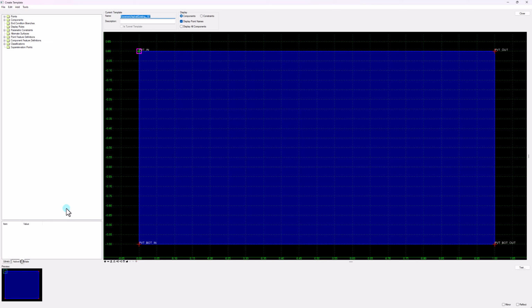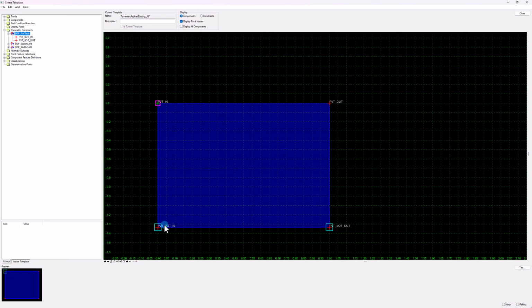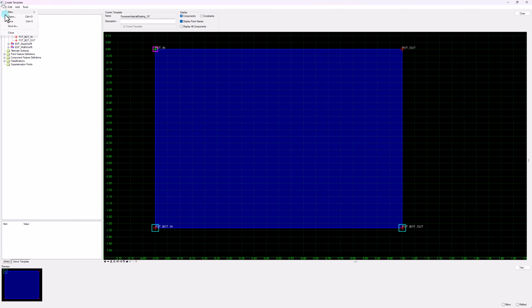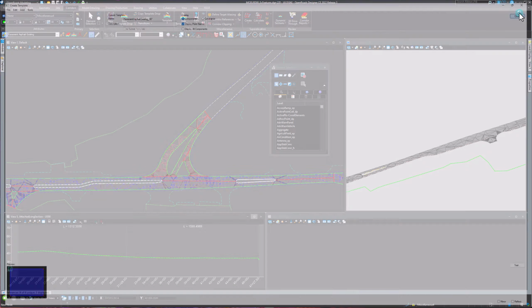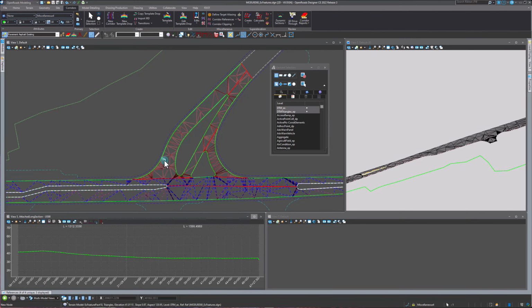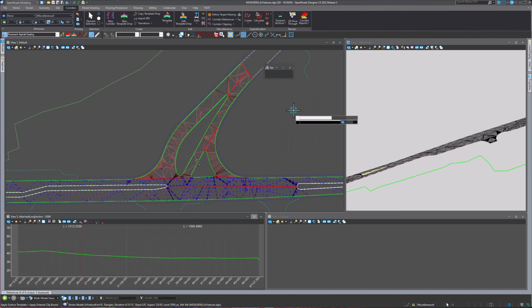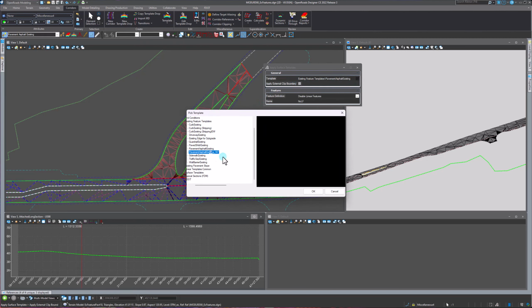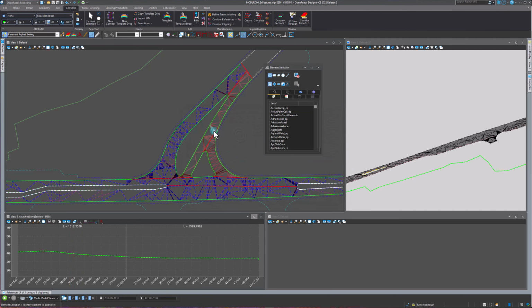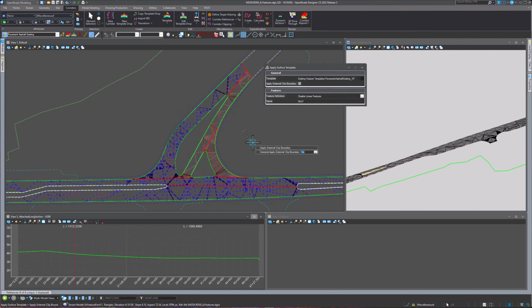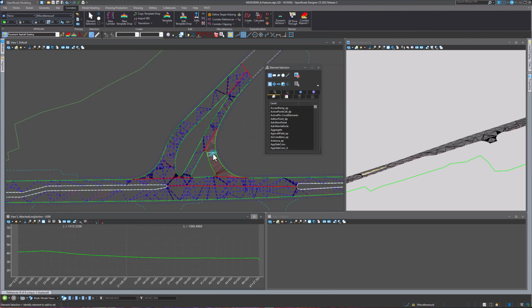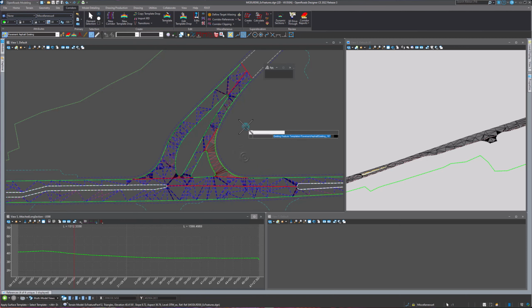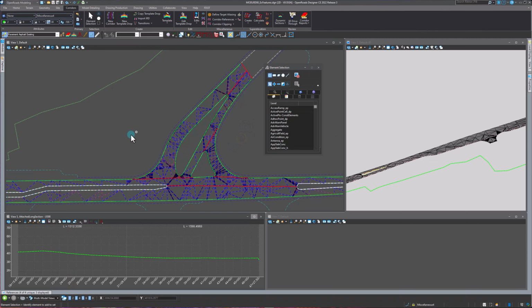And like I said before, you could go into this active template, go to those parametric constraints, and this still works within the template. So if I click on that and type -16/12 and hit OK, now I've got that added depth. If you go File, Save, and Close, now we should be able to apply that surface template to these additional areas up here. So this is where looking at your pavement cores comes in, and you can always adjust this later on the fly.